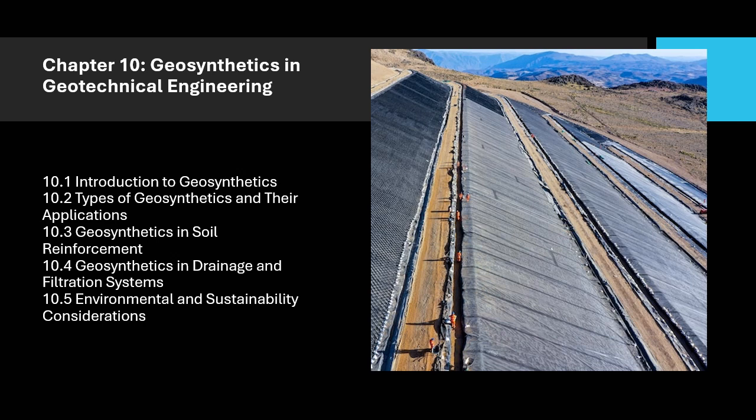Geosynthetics used: geotextiles, geogrids, and geocomposites. Benefits: geosynthetics increase the lifespan of roads by preventing the mixing of soil with aggregates, improving load distribution, and reducing settlement. 3. Slope reinforcement. Description: Geosynthetics are used to reinforce slopes and prevent soil erosion, especially in areas with weak or unstable soils.